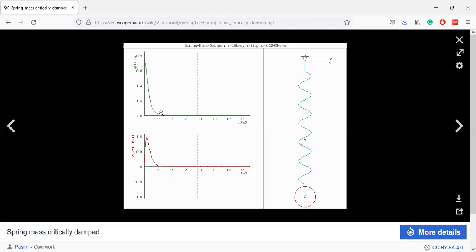The second case, in the case of damped vibration, is when it is critically damped. When it is critically damped, the zeta value is equal to 1. So that we can calculate and find. During that time, the amplitude of this motion immediately goes down within the first cycle and goes in the form of an asymptotic approach to the time axis.